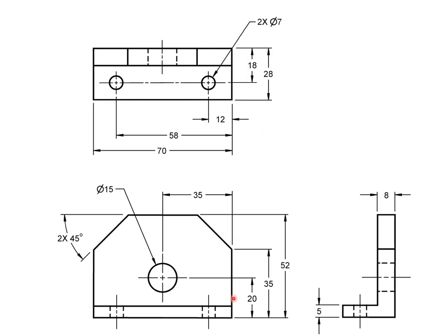Okay, we also decided to go with the datum on the right hand side, so that's what we come up with, 35, from the right datum to the center of the hole. Same thing with locating the first hole. Right datum, center of hole, right datum to the second hole, and finally the overall length of 70. Notice here we didn't use continuous dimensioning.